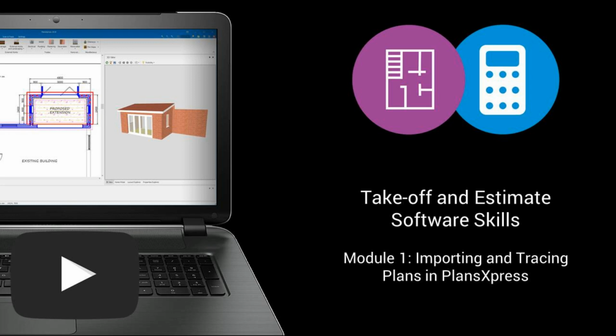So welcome to Module 1 of the Takeoff and Estimate Software Skills course. In this module, the intention is that you'll learn how to import some PDF plans into PlansXpress, and you'll learn how to scale the drawing. You'll practice tracing over walls, windows, doors, structural openings, and you'll have a go at drawing a lean-to roof.